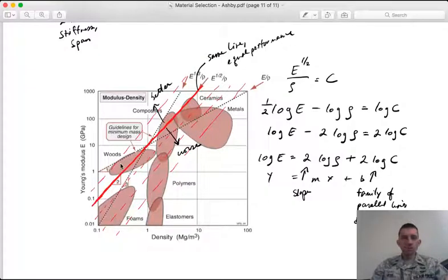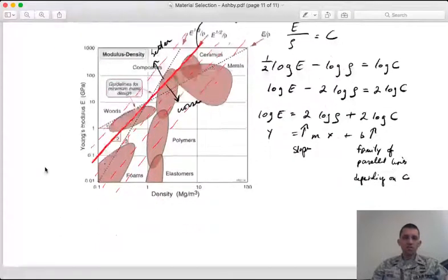Now, for wood, we would probably have a larger cross-section, but remember, every point on this line has an equivalent value for C, right? So that's enough to kind of put both composites and wood on our short list, in which case we would start researching things like cost and availability and lifetime and those sorts of things to choose between a much shorter list of materials.